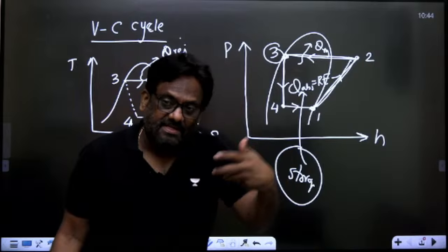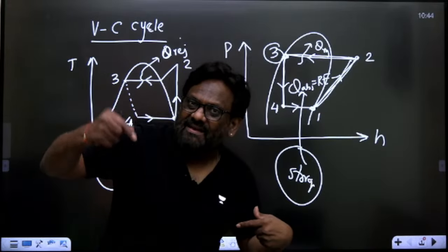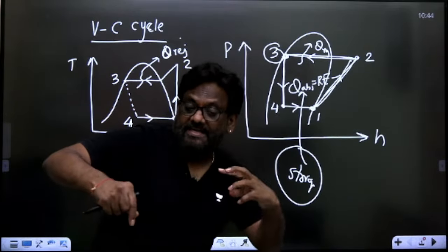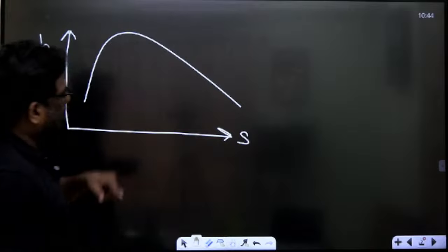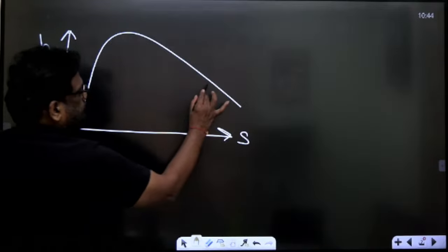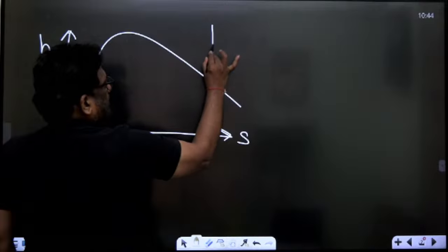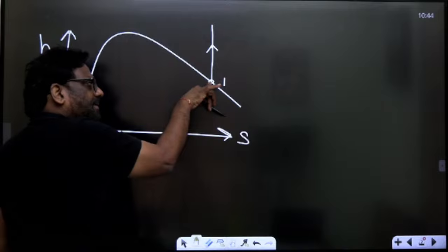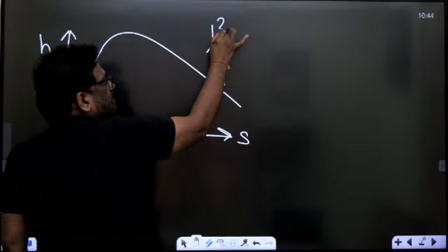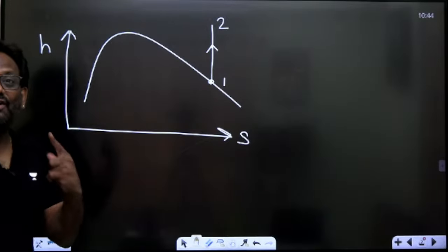Why is the enthalpy increasing? We are giving input to the fluid, sir. When you are supplying energy to the fluid, its enthalpy is increasing. That's why the enthalpy is increasing. So how should I show? It is isentropic. Look once. Yes, this is 1. Saturated vapor is being compressed to 2. It is compression. And now you tell me what is 2 to 3.